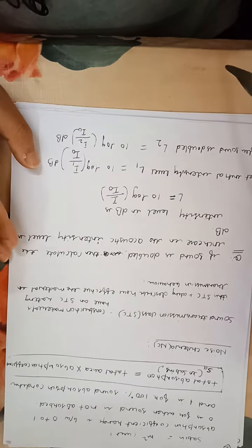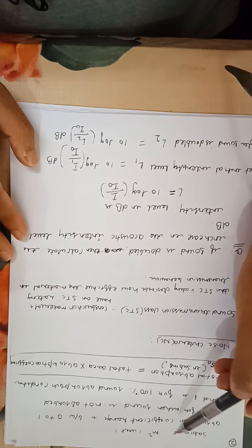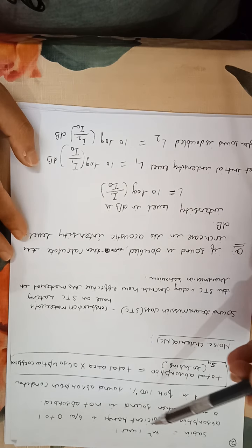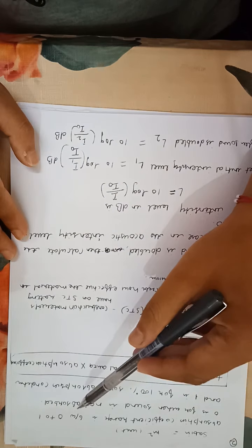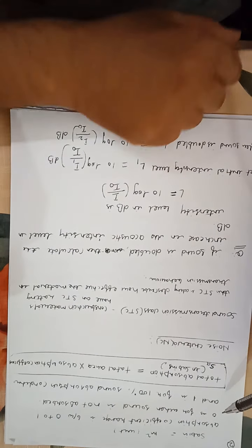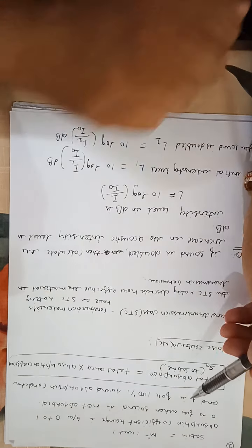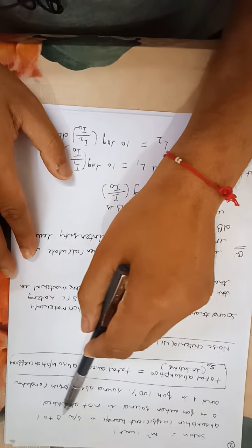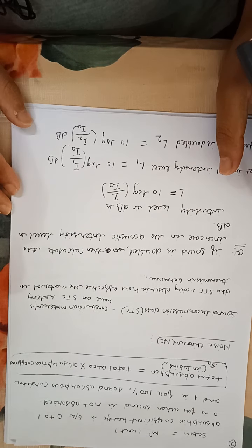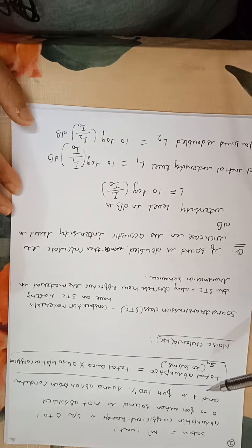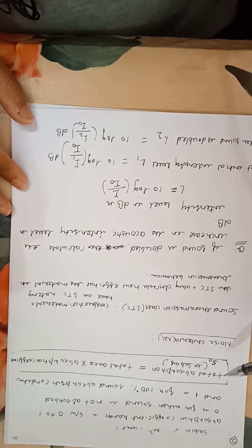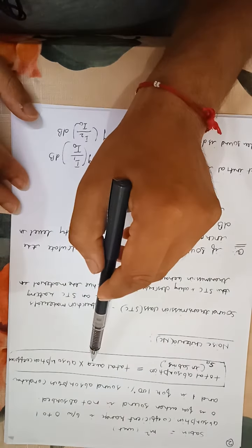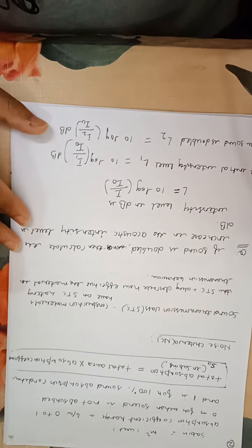Now, Sabins, the unit is square meter. The absorption coefficient range is between 0 and 1. 0 is for when sound is not absorbed, and 1 is for 100% sound absorption. If the absorption coefficient is not given, we sometimes assume it. So total absorption in Sabins is total area into absorption coefficient, total area into absorption coefficient. And we also